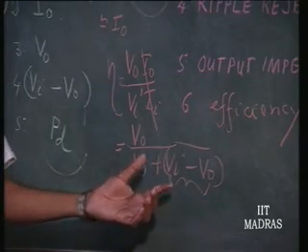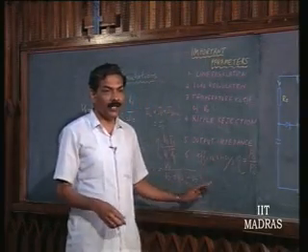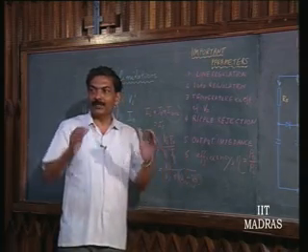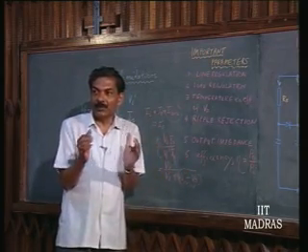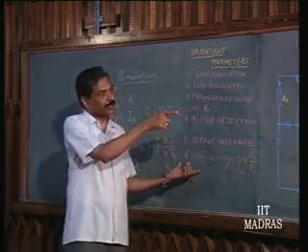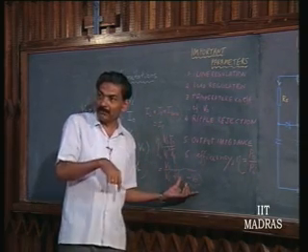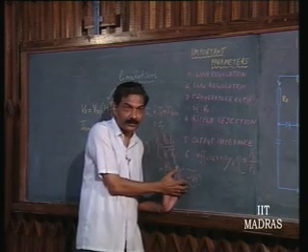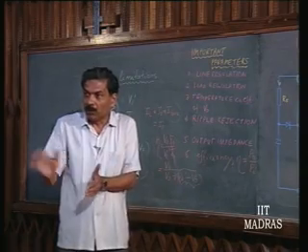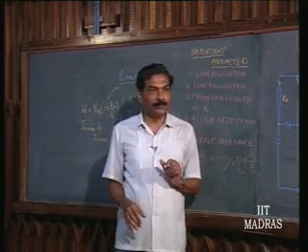This is what is called a differential voltage. This differential voltage is important in the case of voltage regulators, and it is given as Vi minus V naught differential. That there is a minimum. You cannot make it lower than a certain value. So, what is that limitation? Let us look at the circuit now. That limitation on Vi minus V naught minimum, this has to be made very low, that we understood. So, can it be made as small as we please? No. Given a circuit, we can find out what this minimum is going to be. Let us see that.